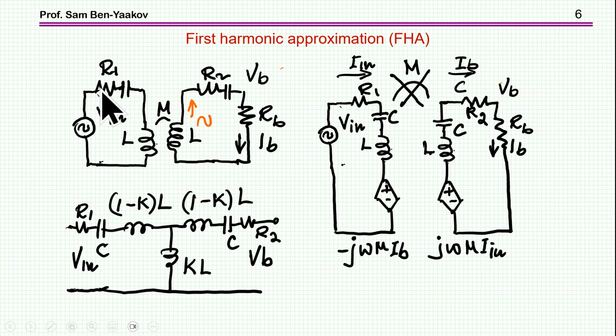We have these are the parasitic resistances. Well, at high frequency you have to consider the RAC, the skin effect, of course. And then we have the resonant capacitor, and these are the inductances. And here already I've put the first harmonic approximation representation.